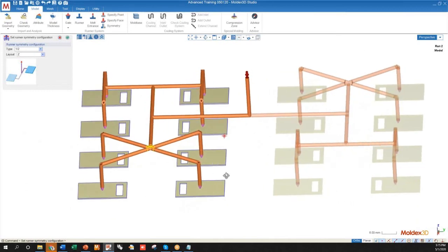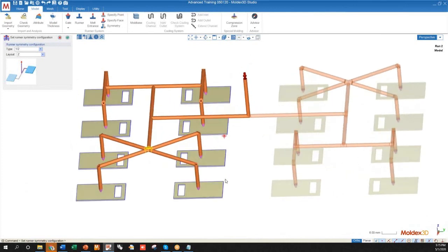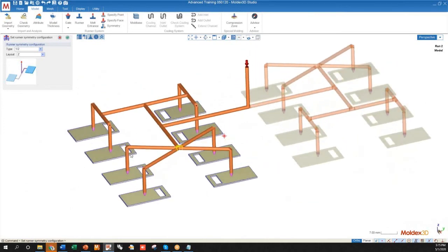It's just the pressure required to push the material that far into both sections is going to be doubled. So we're going to take whatever pressure is required to fill out this system, double it, and that would be the exact molding scenario as doing a 16 cavity mold instead.